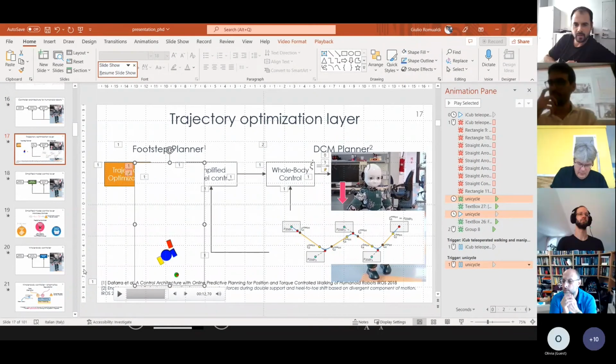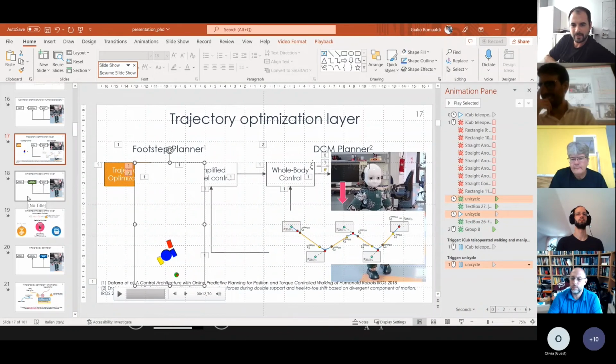But I mean, one thing is the force measurements, but the other thing is that what you're presenting here requires an extremely precise state estimation. You have to measure the deflection of the ground contact, which comes through a state estimator of a body on a compliant surface, whereby the state estimator itself typically makes assumptions about the environment. Is it feasible to run something like this ever on an actual physical system? Because you're talking about centimeter or even millimeter precision that we need to have a proper contact.